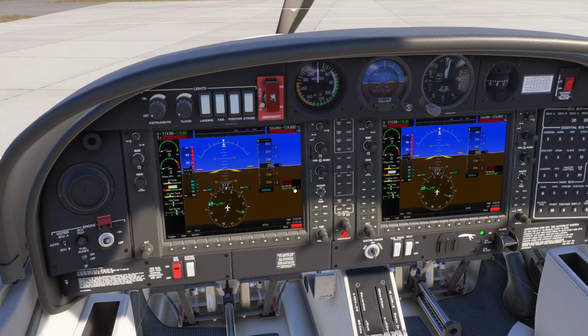The glow will be on. The annunciators are normal. The glow is now off. We can now start our engines. Hold until we get 700 RPM. Release it. Oil pressure rises in the green. RPM 700 plus or minus 20, and load 1%. And that is how you start the engine. Now we've checked all that, the guard can go on.